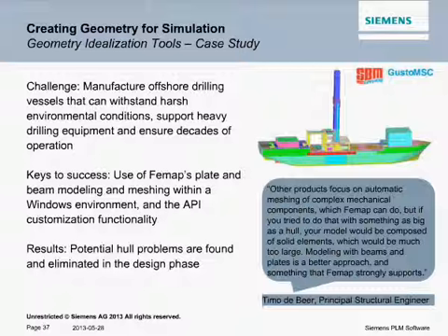So the keys to success here was the use of FEMAP's plate and beam modeling and meshing. They mentioned the Windows environment here, and also the API, which I mentioned a bit later on. This is the application programming interface, another powerful aspect of the FEMAP program. And the results, potential hull problems using this modeling approach could be found and eliminated very early in the design phase.